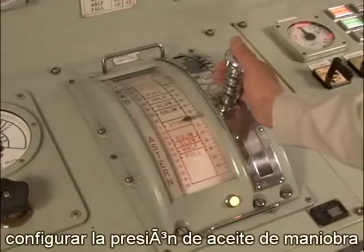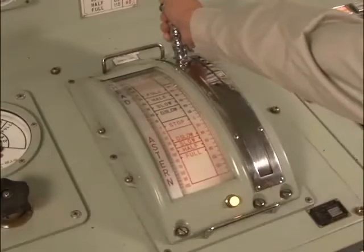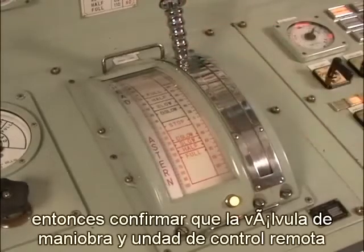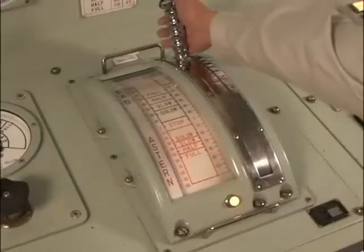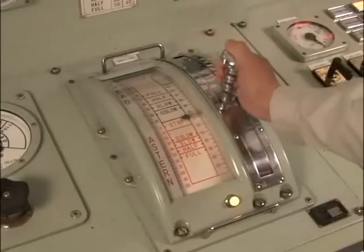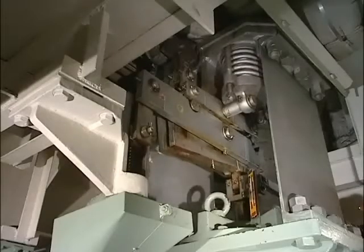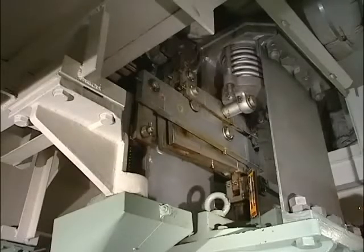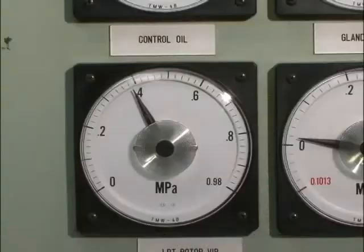Set up the maneuvering oil pressure. Manipulate the maneuvering lever in the control room. Then confirm that the maneuvering valve and remote control unit are in good working order. After the confirmation is over, trip the maneuvering oil pressure.